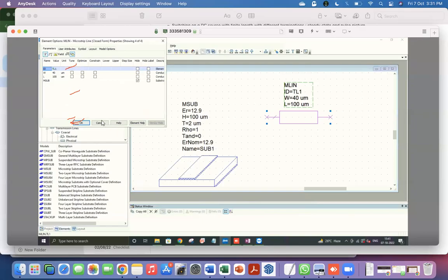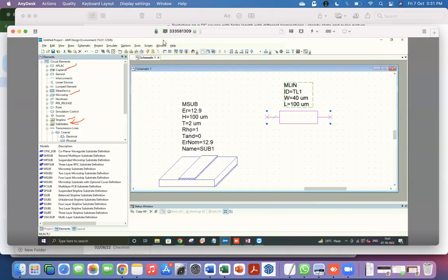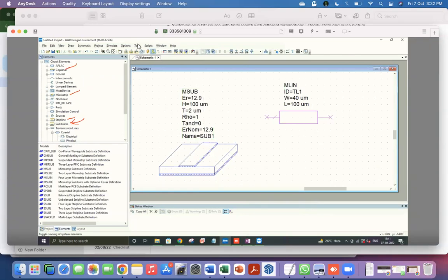But those kinds of simulations in this physical model, where you have different substrates, might have other complications, because it's not just about the signals from the center conductor, but how the grounds are interfacing. That could be complicated. So it's best that you do a full EM structure simulation where the whole thing is completely defined. Okay, so let's look at that.